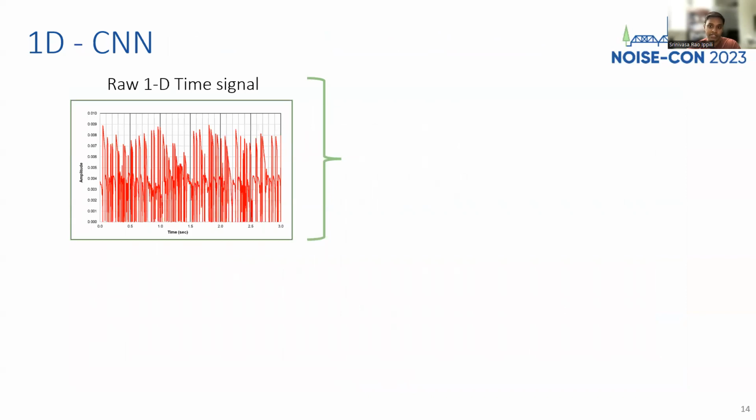Some of the recent literature demonstrated that the original two-dimensional image-based CNN concept could be harnessed on one-dimensional sequences of data as well. The outstanding benefit of using one-dimensional CNN for motor fault classification is that they can learn from the raw time series vibration and acoustic data directly without the need to perform the data transformation to a frequency domain. A good CNN model will learn an internal representation of the raw time series data and ideally achieve comparable performance to these models fit on a version of the data set with human expert dependent engineered features.